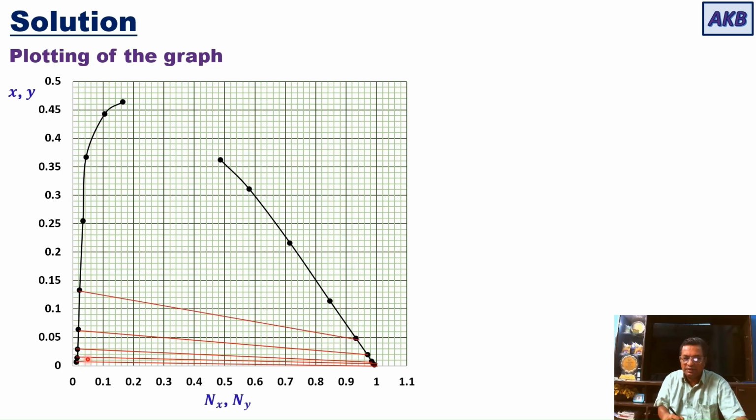And then I will be connecting the corresponding equilibrium concentrations in raffinate and extract phases with these tie lines. So the composition in raffinate phase, this, is connected to the composition in extract phase, this. So this composition in extract phase is in equilibrium with this composition in raffinate phase. Likewise, I have drawn all the tie lines that are given to us. Please remember, tie lines connect concentrations in raffinate and extract phases that are in equilibrium with each other. So we will need this ternary equilibrium diagram.